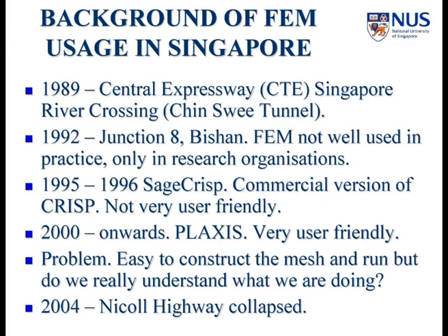You never need to know anything about the stiffness of the material, like the modulus or constitutive model. You don't even need to know the K0, the lateral earth pressure coefficient. All you need to know is c', phi', or c, phi, something like Cu, phi u, that kind of thing. Basically, all you need is the strength parameter, because you're really designing against stability and you just want to have a factor of safety.